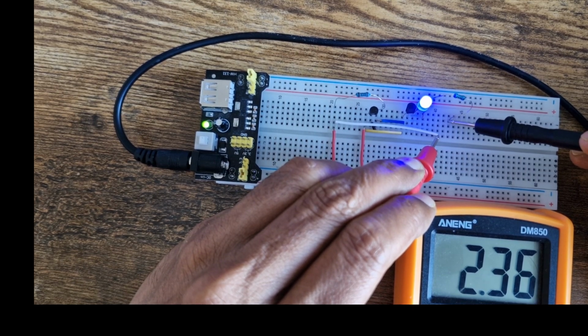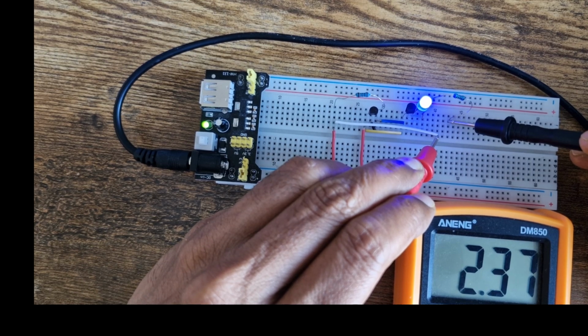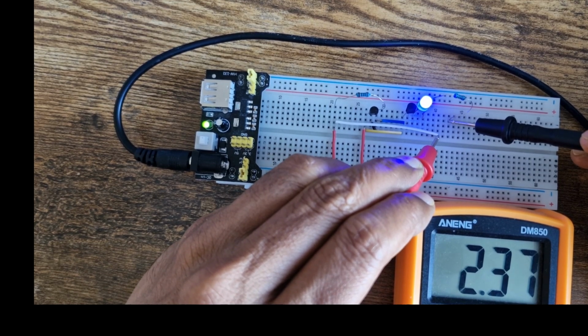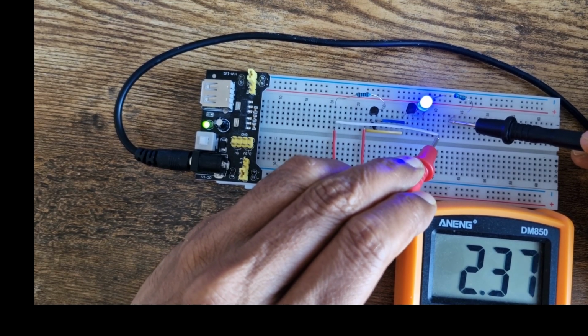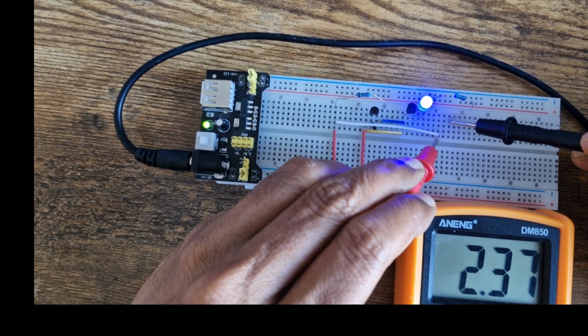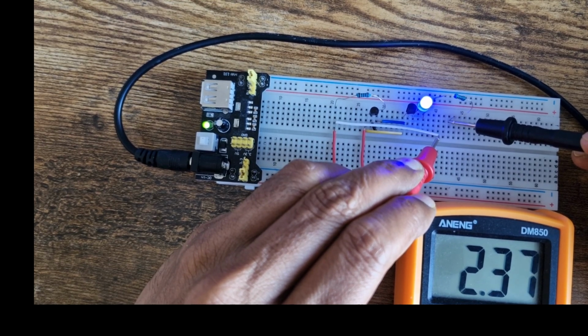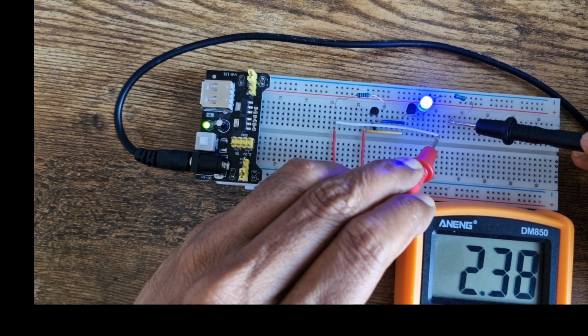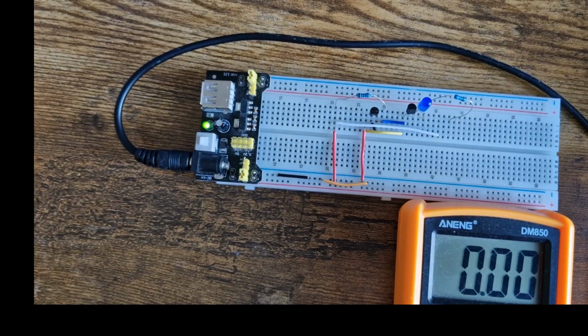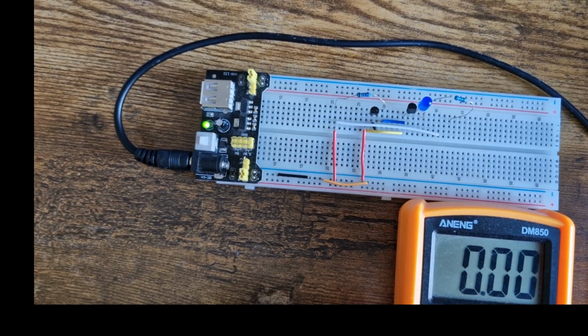Just write that into the comment section. The hint is the output resistance of the circuit, right? And there is a minimum voltage across the output part of the circuit that you have to maintain to keep the circuit working as a current mirror.